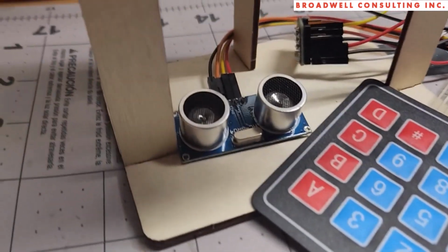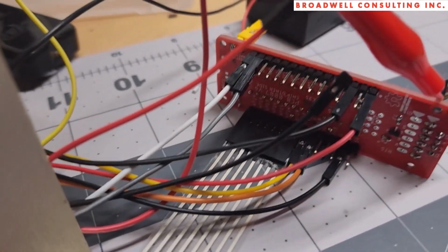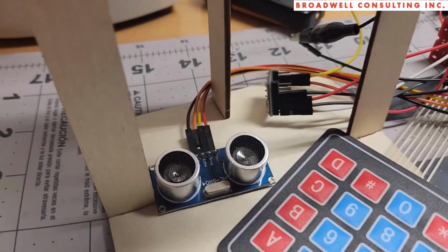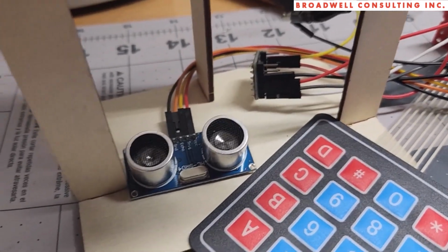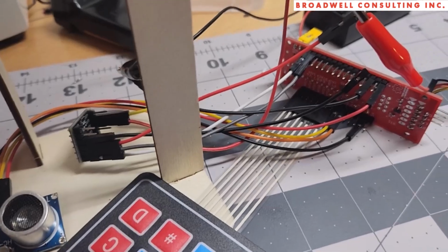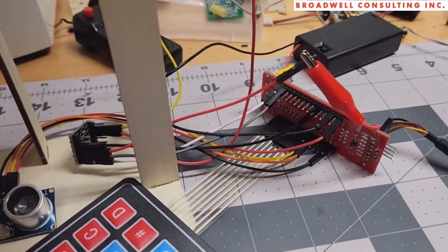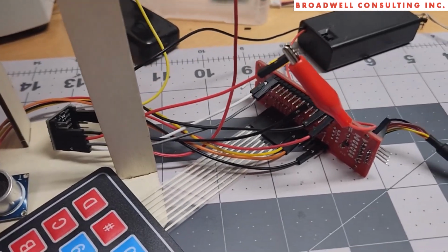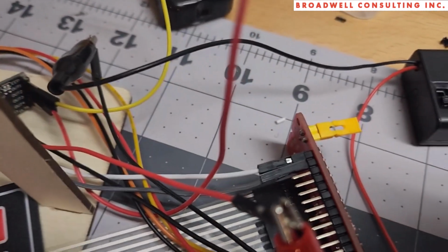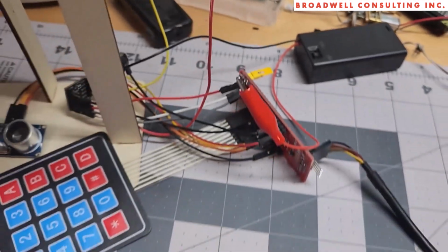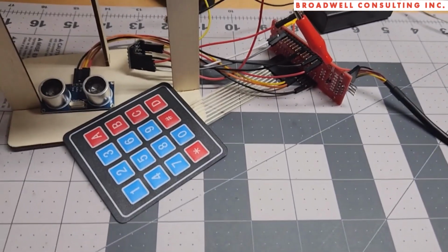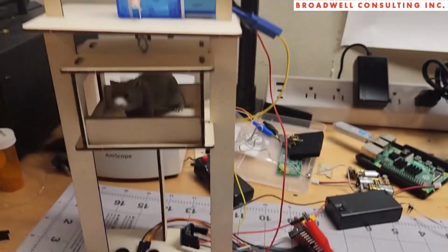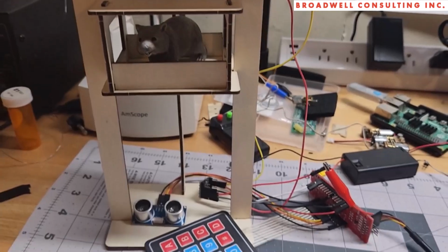We've got the HC-SR04 hooked up to pins 10 and 11. That's important because this is a 5-volt sensor running off the 5-volt supply, so we go into one of the 5-volt tolerant pins on the Serial Wombat chip. We're running the H-bridge off of pins 0 and 1, which are both enhanced digital performance pins, which is good so that we can get high-res PWM. So that's about it for our physical plant.